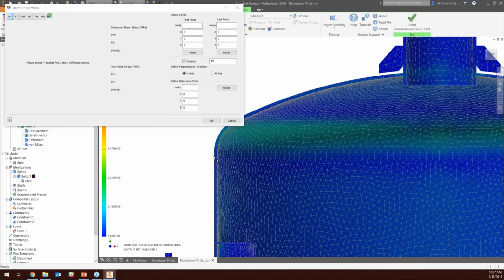So it's a little interesting when you're looking at welds. You want to be able to represent them as something that's close to them, but not actually represent them as welds per se. So typically it makes sense to use a combination of line elements and shell elements as opposed to solid modeling a weld. It's something that takes some explanation before you can wrap your head around it. And that's exactly why we said, if you have questions on welds, feel free to contact us, because it's a completely different sort of workflow.